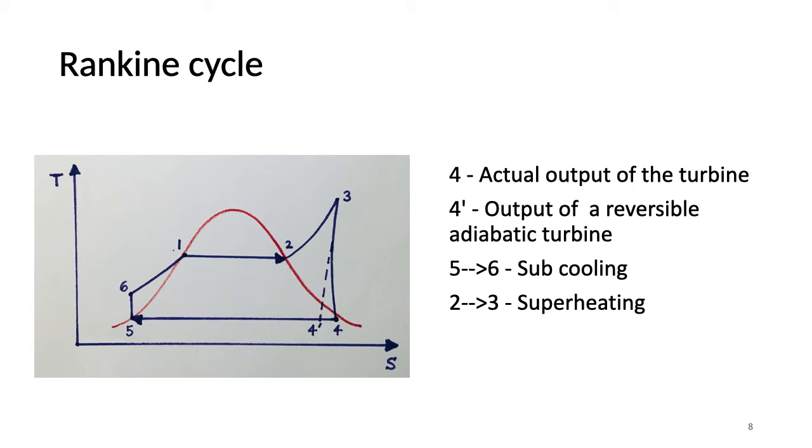It is impractical to use Carnot cycle when the water is used because compressing a partially condensed liquid is more complex than compressing a completely condensed liquid, and wet steam, which is a mixture of water and steam, damages the turbine blades by erosion due to water droplets. Due to these reasons, power plants use modified Rankine cycle.